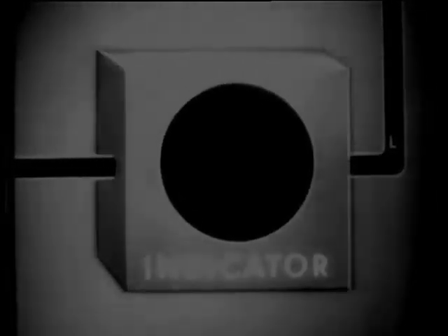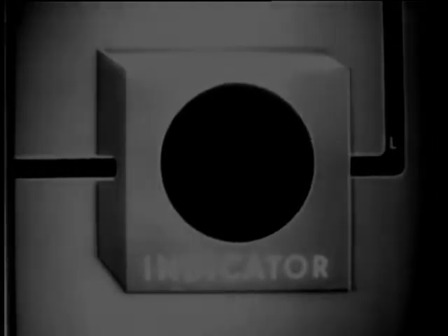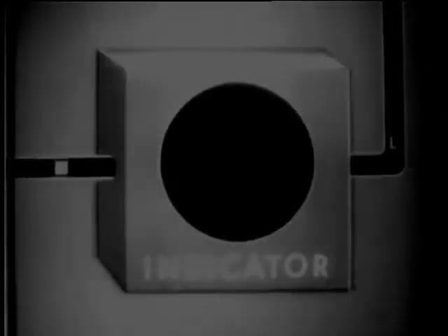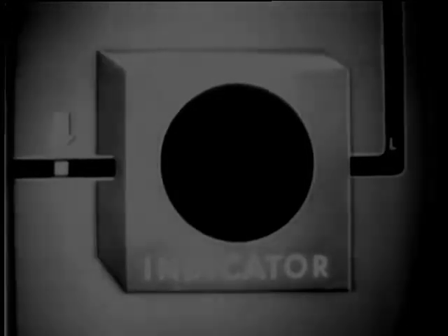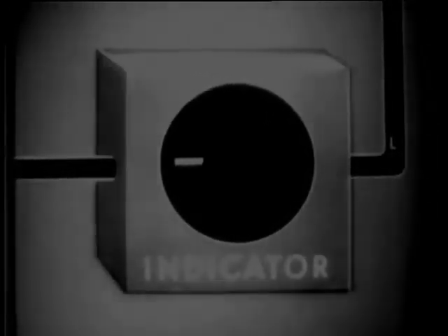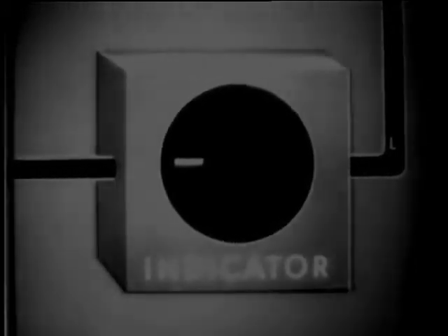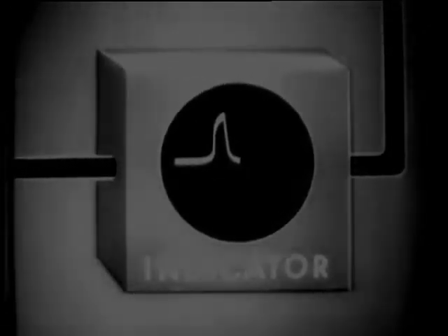Before they appear on the scope, the indicator must also be prepared to receive two echo signals and display them separately. Here's how the indicator works. When a pulse was sent out through the left lobe, at the same time, part of that energy was sent over to the scope, where it began forming the baseline. Thus, when the echo from the left lobe returns, it forms the pip on that baseline.